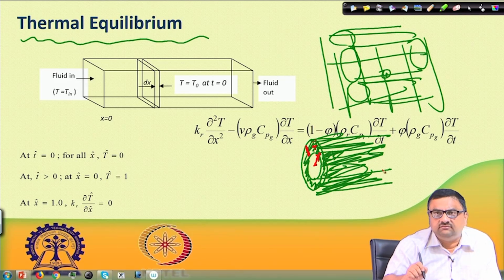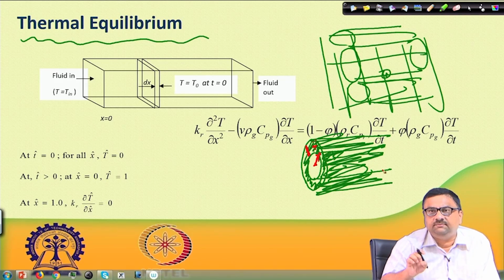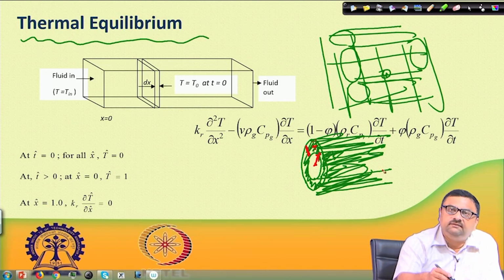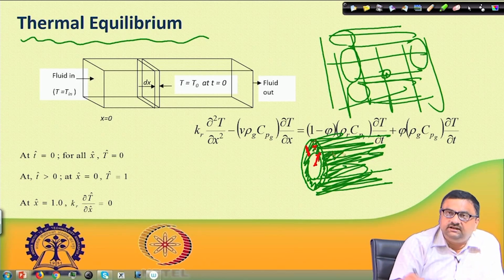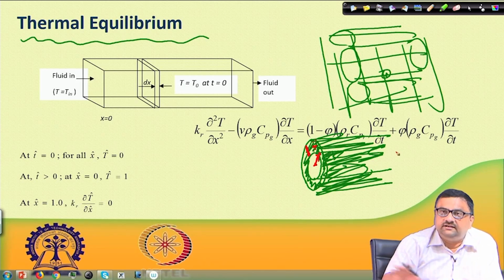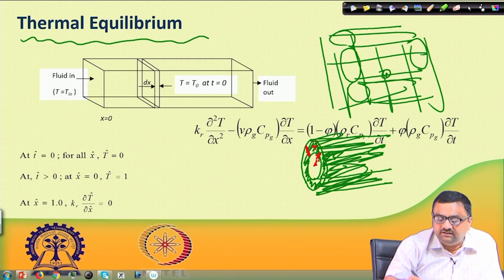This is how things are happening inside a capillary, and this must be happening inside a porous medium as well, right. Now, what we are assuming instead is that this porous medium is a continuous homogeneous medium, and it has temperature as a continuous field, but actually temperature is supposed to jump within the fluid and then into the solid, with completely different slopes altogether.